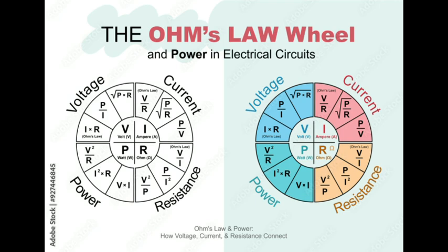I'm gonna color code it. That white conductor is going to be our neutral. And that neutral is gonna go right here to the light. But before we connect it to the light, we have to make a splice